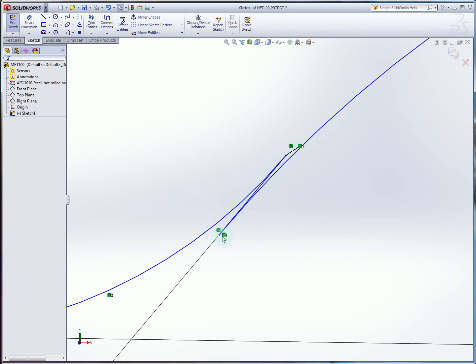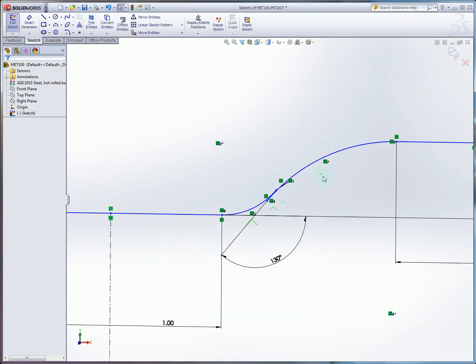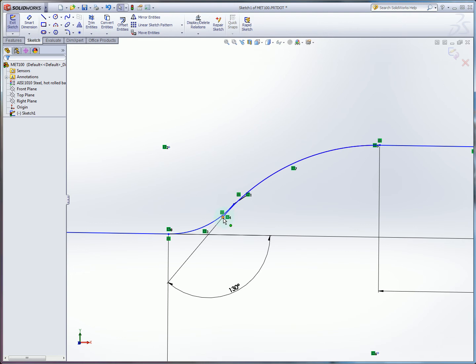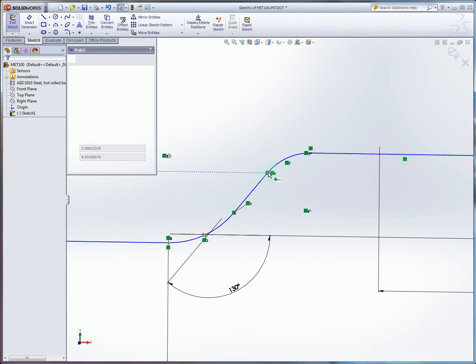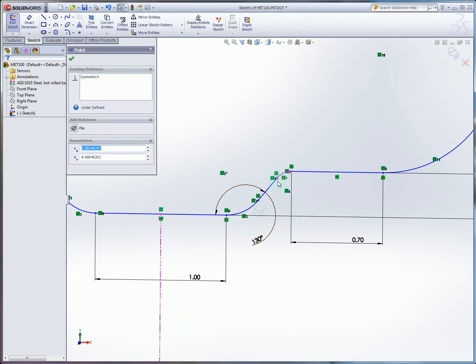This zigzag happens because basically the solver is too unconstrained. It permitted the radii to get too big, and so they actually overlapped each other, despite still satisfying our constraints. Now, all is not lost if this happens, but you have to be able to recognize it. Usually it's enough to just drag the feature towards what you want, and then you can manually restore that shape with a quick flick of your mouse.